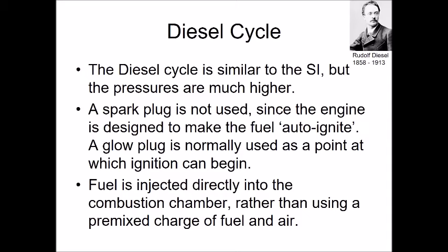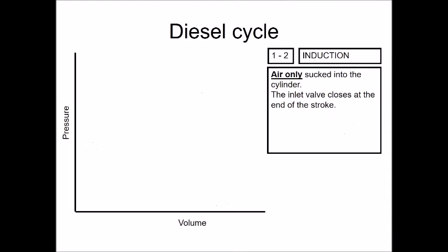So with diesel as well, fuel is injected directly into the combustion chamber. We don't use a pre-mixed charge. So the air is squashed, and as it's being squashed, we throw the fuel in as well, and we're going to look at some of that later on. Okay, so that's the diesel cycle. Let's just take another look at it in a diagrammatic form.